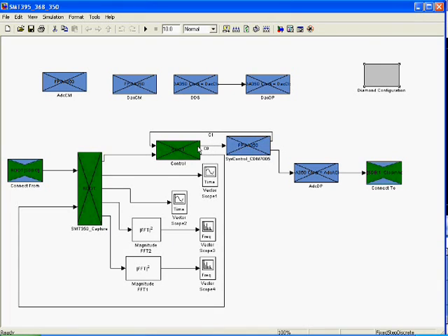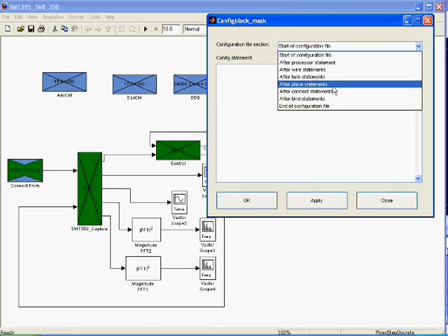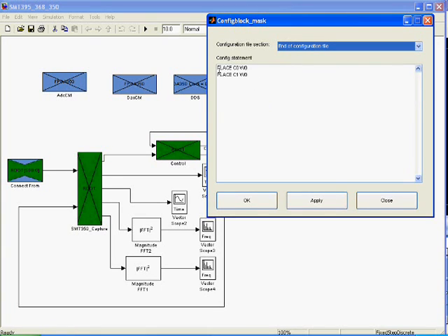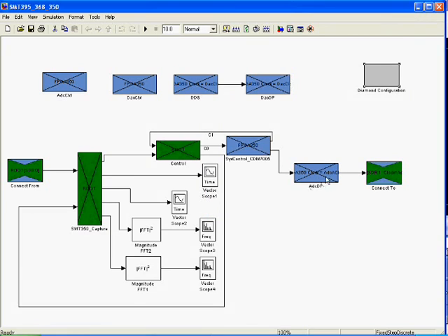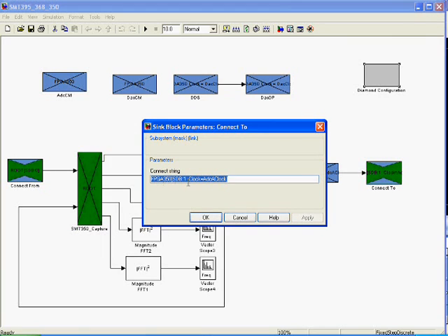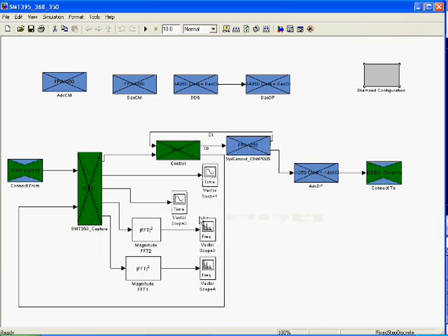Also, remember to declare the channels between the DSP and FPGA tasks. The high-speed channel is described using the Connect To and Connect From blocks. These blocks can be used when communicating with a non-Sundance I/O device.